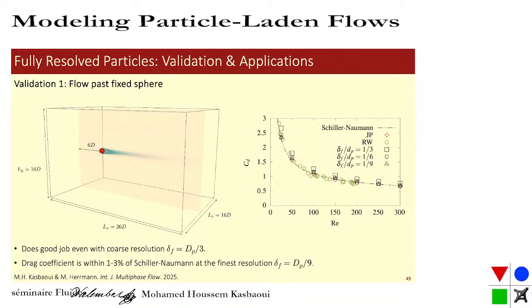Okay, that's a really good question. With this formulation, we kind of separated the grid resolution from the simulation resolution. The simulation resolution is controlled by the filter size. You can have a lot of grid points and continue refining, but you're not going to get better resolution because that's controlled by the filter size.